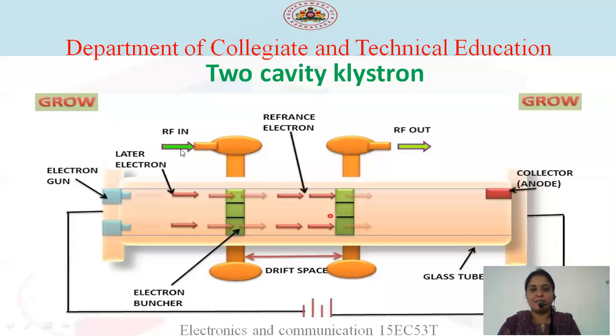If you observe here, the energy is applied, and the bunching of the electrons is taking place. Once they reach here, that bunch of energy is applied to this output tube or the cavity. Now this output cavity is also oscillating same as the input. The frequency will be the same, but with much higher energy, because all the bunches are together here. Electron bunches are providing their energy here. Therefore, the output will be a much higher signal.